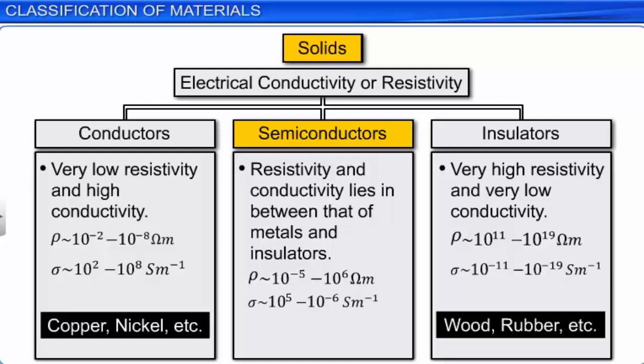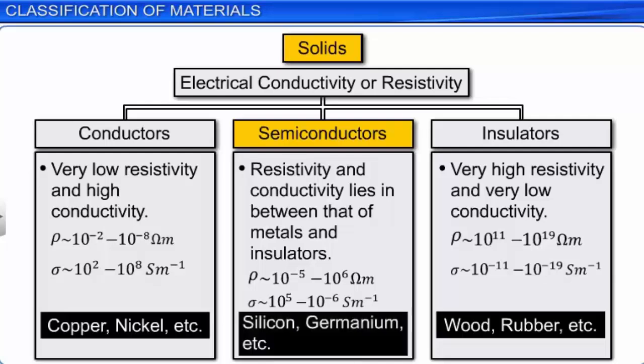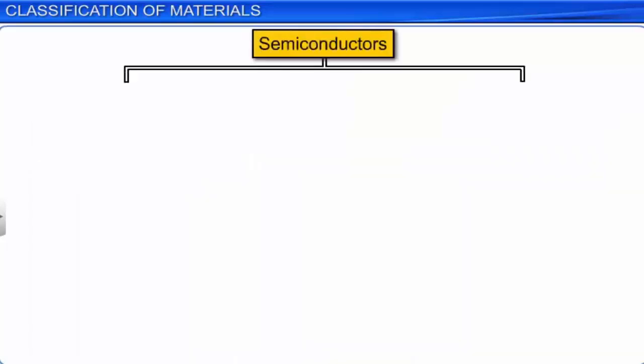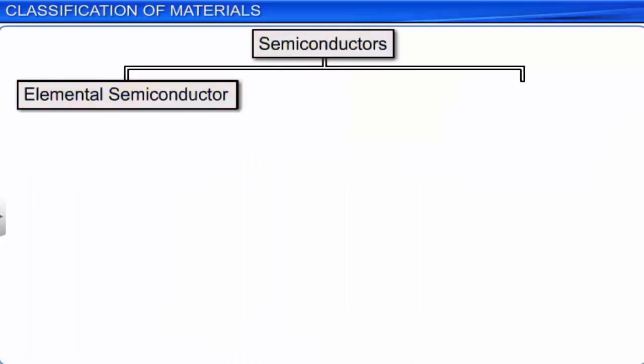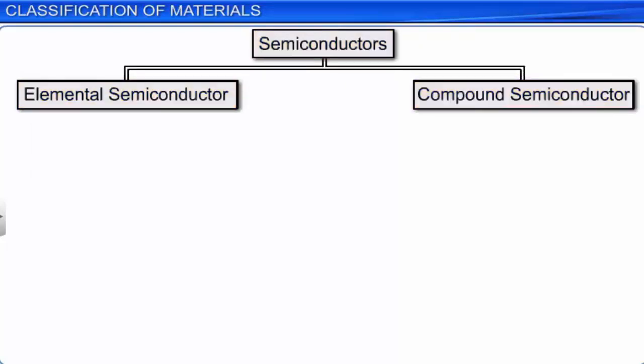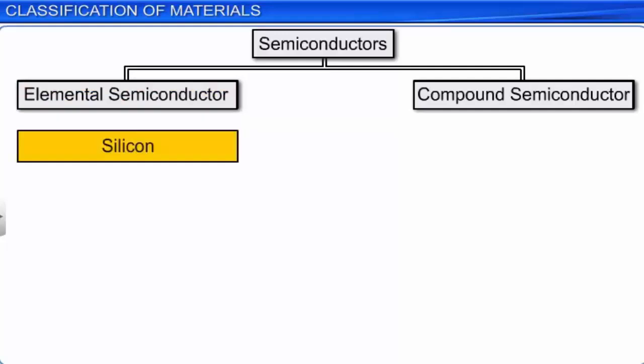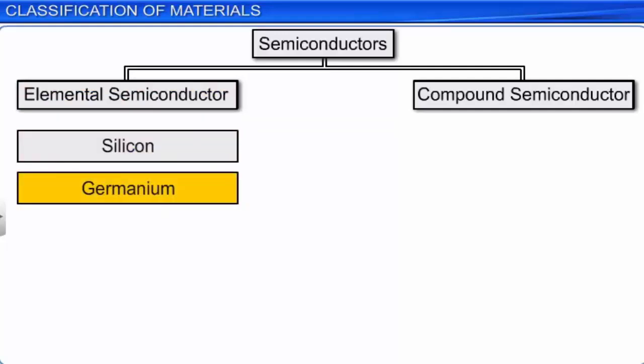These semiconductor electronic devices may be made up of different types of semiconductors, such as elemental semiconductors or compound semiconductors. Elemental semiconductors are single elemental semiconductors. They belong to the fourth group of the modern periodic table of elements. Silicon and germanium are the most commonly used elemental semiconductors. Compound semiconductors are formed by using two or more elements. They are synthesized using elements from groups 2 through 6 of the periodic table.